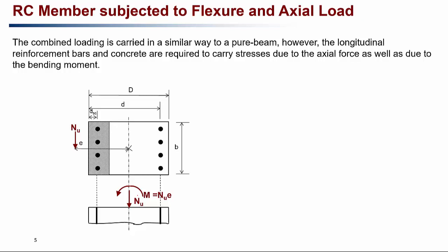So as you can see, if there is a bending moment acting on this column, that means this portion of the column will be in compression because the column is trying to bend this way. So that means this will be in compression and this side of the steel is in tension, right? And as a beam, as you can see, the left portion is in compression, and there is a compression block of concrete that is taking the compressive stresses, and the tensile stresses on the right hand side are taking the tension stresses now, right? It is very much like a beam, except that there is axial load Nu also acting on that column, unlike the beams.